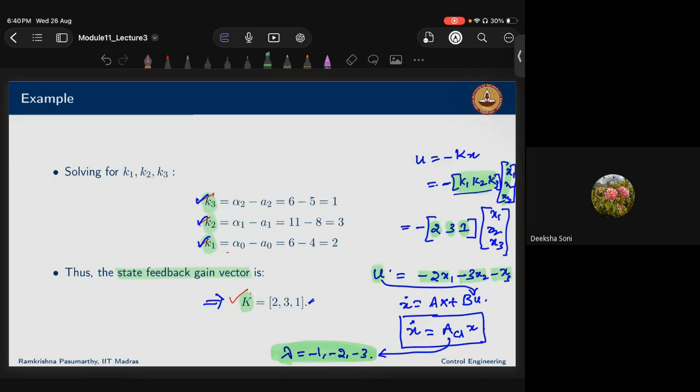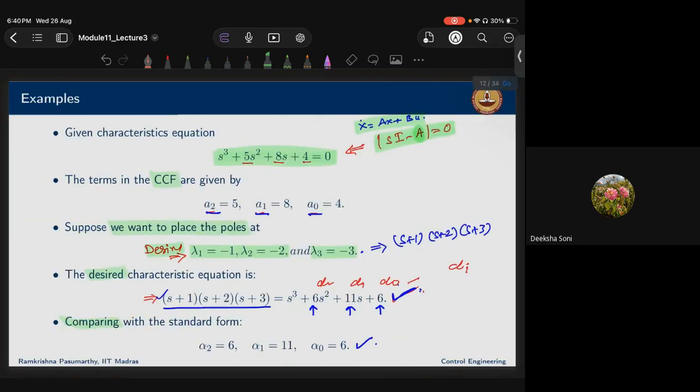So substitute this u in the basic equation. For this ACL, if you find the eigenvalues, again you'll get the same values, -1, -2, -3, which are nothing but the desired pole locations. Is this clear? If you just solve this example, you'll understand it. This is method 2.